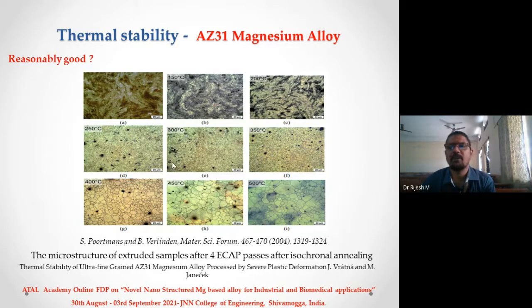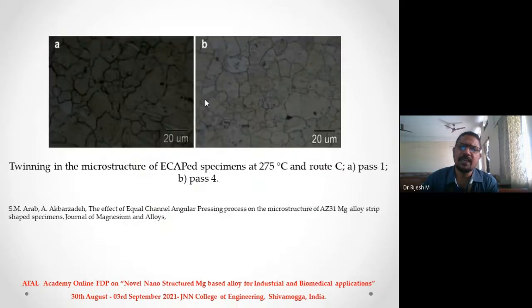When you anneal your material, this annealing is very important. Don't you feel that going for a second pass and third pass becomes so tough? Pass 1 has a lot of twin bands. It's difficult. Pass 2, again, plenty of twin bands is difficult. After pass 4, it may break. So what I do is I relieve the stress a bit by heating to a higher temperature.